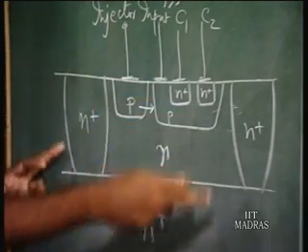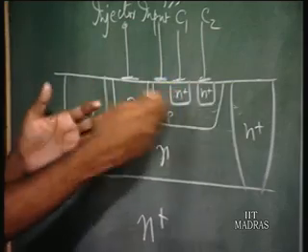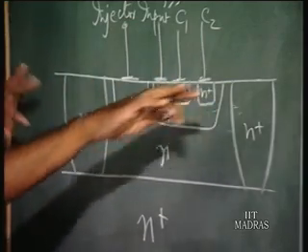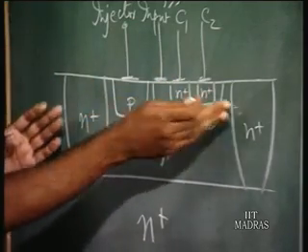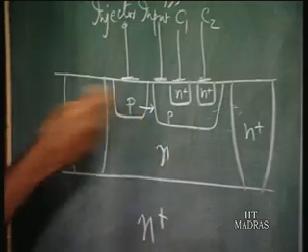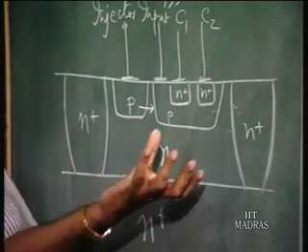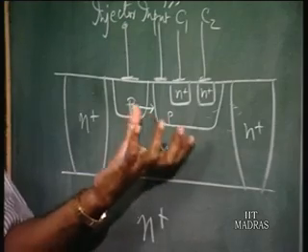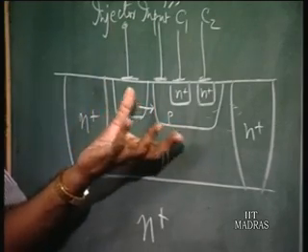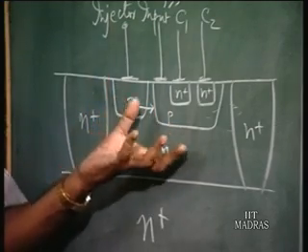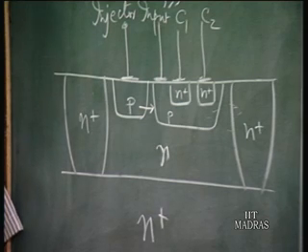So you make a guard ring. So all the activity is confined to this region, and there is no injection of charges on these sides, which is actually going to be a waste and reduce the performance of this circuit.